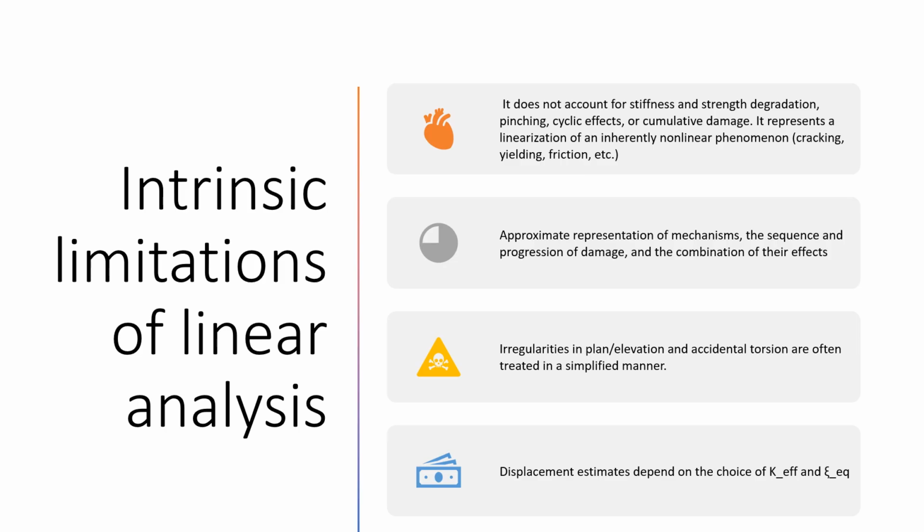As we were saying before, displacement estimates also depend on the choice of the effective stiffness, which is an elastic stiffness reduced to account for cracking and for other aspects that can be quite complex, and equivalent viscous damping that accounts for different sources of energy dissipation.